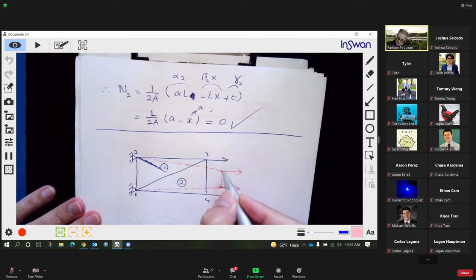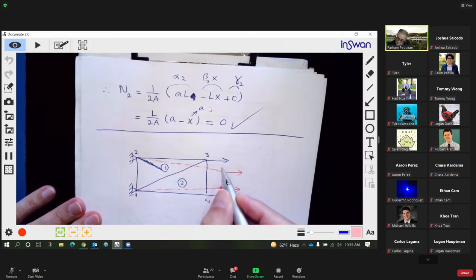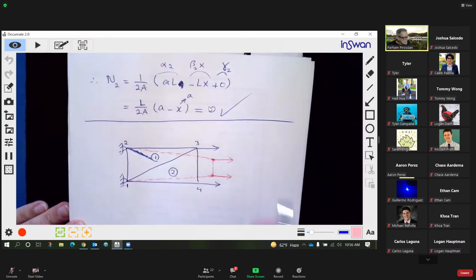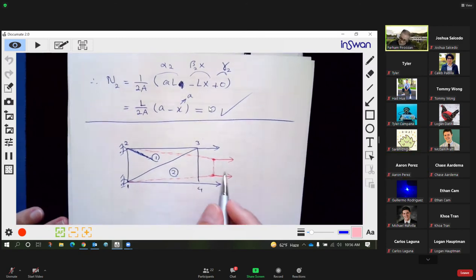It shrinks here because of what? Longitudinally, we are stretching this, but laterally there is contraction because of the effect of, we call it what? Poisson's ratio? Poisson's effect. All right, very good. So we should get a displacement like this, but the displacements that we got are not really good. This discussion is of course important. I want you to see the behavior of this triangular element.